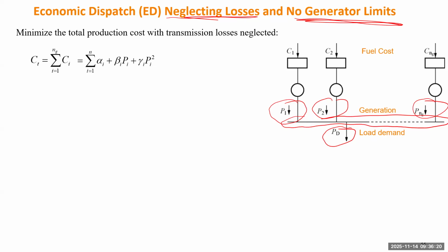And each cost of the power plant is formulated by a quadratic function. To calculate total cost, we simply add all the quadratic functions together. So that will be the total cost of this system. And there's just one equality constraint, where the left-hand side will be the total input, the right-hand side will be the total load.